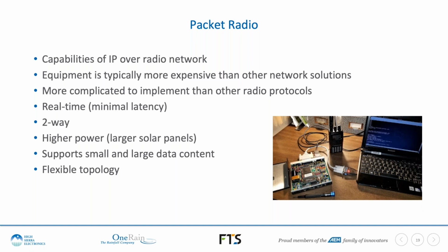It is a real-time system, so the latency on a packet radio network is pretty minimal compared to some of the other protocols, because you don't have to wait as long for the data to get through. It does support two-way, because it supports everything you can do over an IP network. It is higher power because the radio is on all the time, listening and transmitting in a packet radio network.